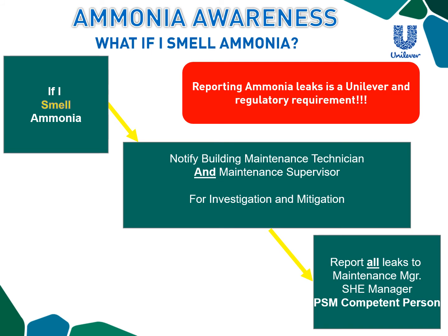If it's something minor, we may be able to respond to it and correct it. If it's something major, we may need to get a hazmat team in. It's also important that we report any leaks because it's a regulatory requirement and it's a Unilever requirement. Depending on the nature of the incident, we may have to report it to the EPA or to other regulatory bodies.